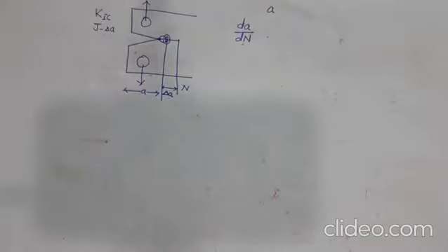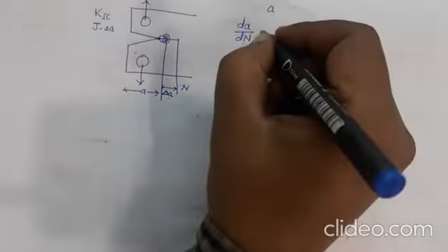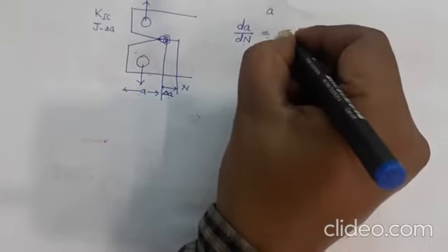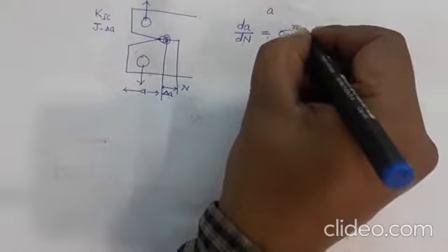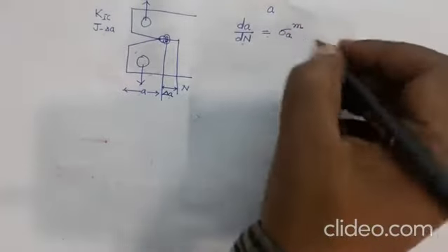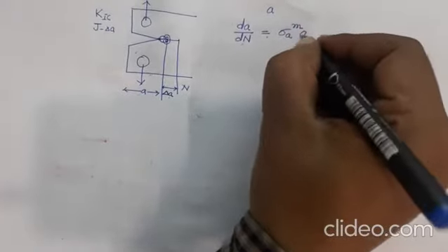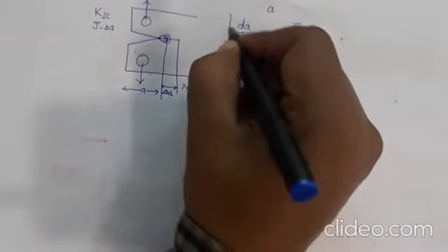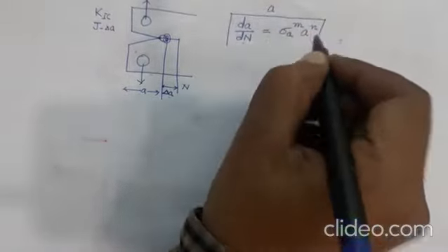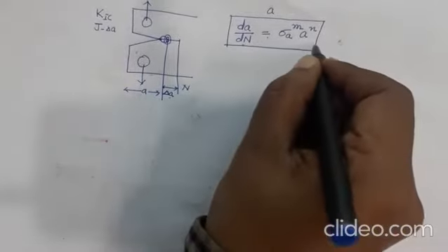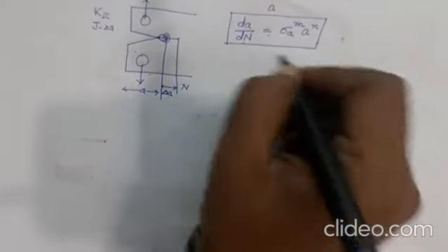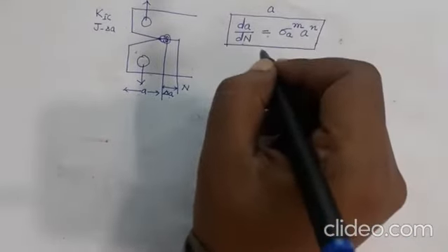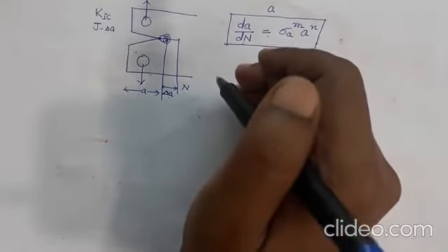This can be related to the amplitude of stress raised to some power, and the initial crack length. This kind of formulation has been suggested to describe fatigue crack growth, but it will not describe fatigue crack growth in the whole domain.